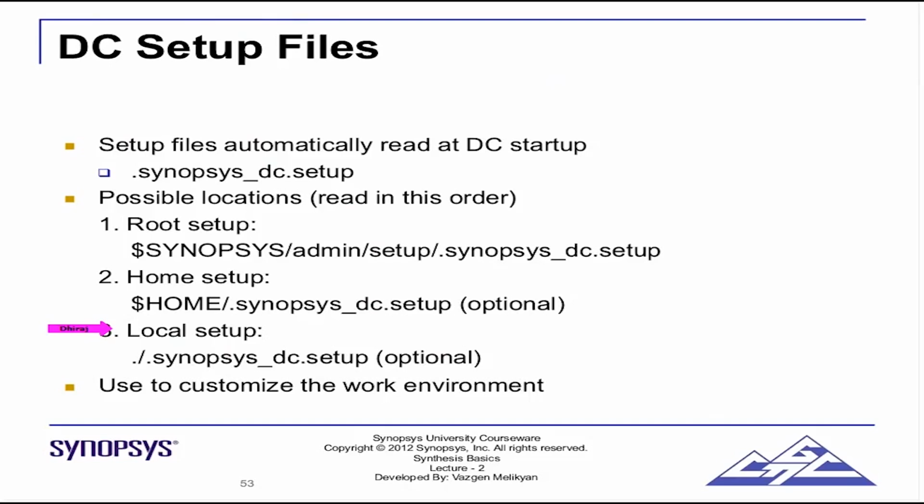Now, let's say I am in charge of a particular project, and 5 guys under me are doing synthesis. I could write up a .synopsys_dc.setup and use it so that each of those 5 guys, when they start DC, they get a similar environment. So I could set my libraries there. This will make sure that each of those 5 guys is using the same set of libraries. So I could do that by using this .synopsys_dc.setup file.